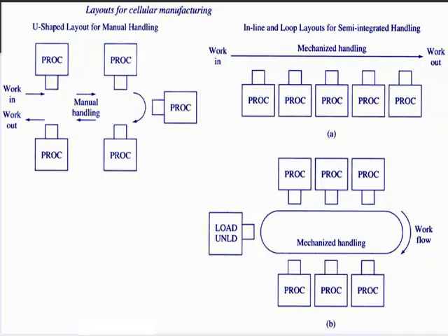The machines or processing stations are kept side by side all along the line. When the work part transfers from one machine to the other and stops, the machining takes place automatically. So the work part moves for some time and stops for some time. A conveyor belt with intermittent stoppages can be used as a material transfer device.